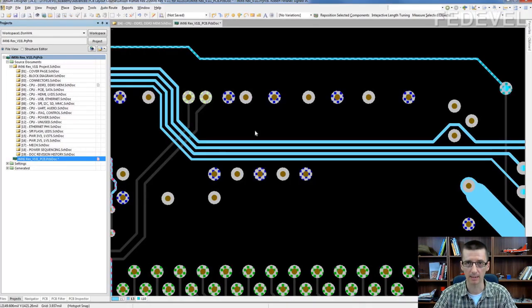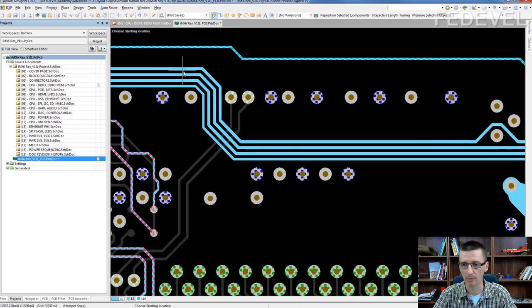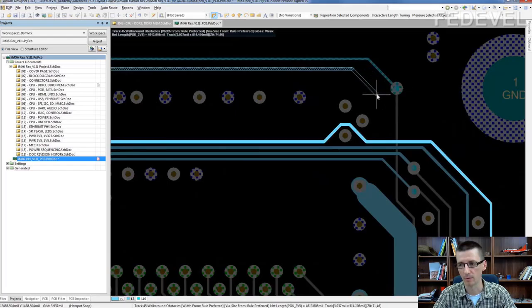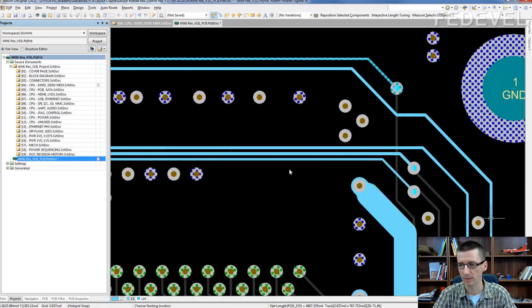Many times I see finished boards with tracks routed like this, with a lot of space around the tracks. To improve your layout, don't leave it like this. Reroute the signals and use the free space. Okay, for example, like this.